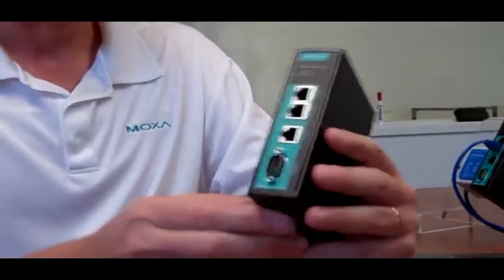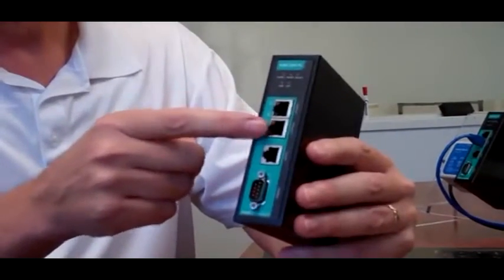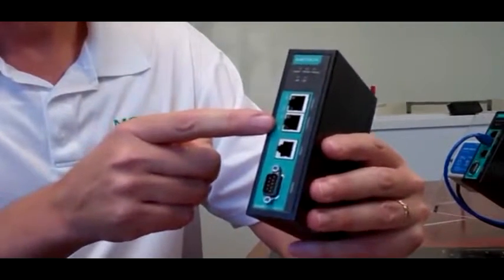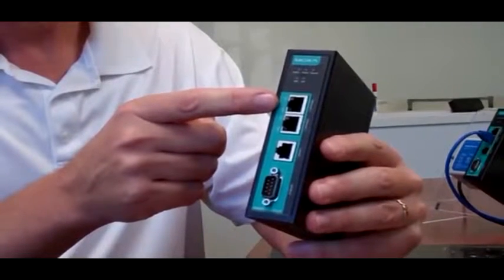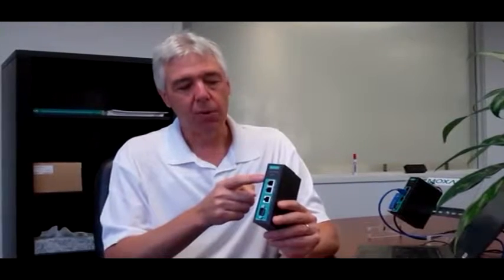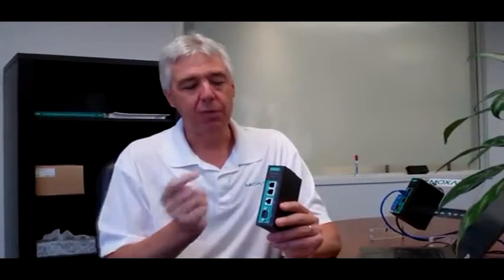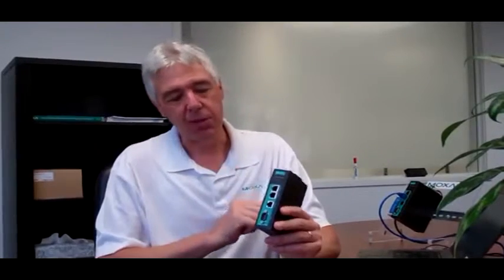Now, this is the MGate 5105, and it has a couple unique features on it. We talked about the serial interface and Ethernet. You may notice there are two Ethernet ports here. That can be used in applications when you may want to interface via Modbus TCP to the second device instead of serial. Or more commonly, a lot of people like to use this for bridging multiple devices. It's a built-in switch, meaning you can have a drop into the panel for one connection and then have your PLC on Ethernet for the second connection.